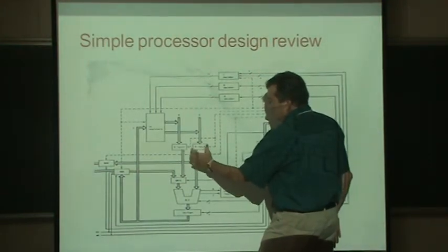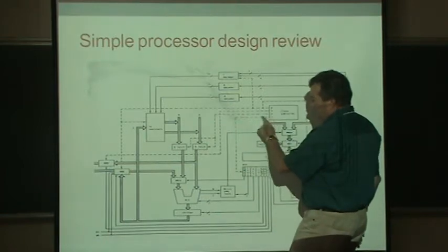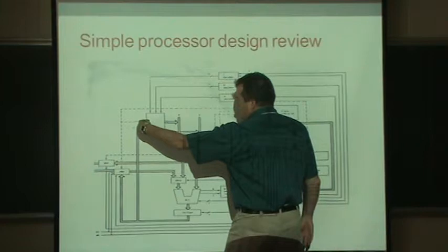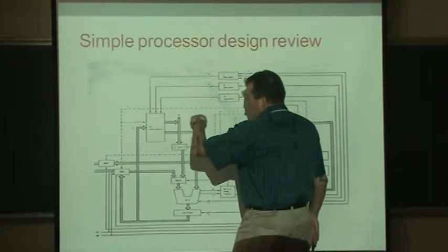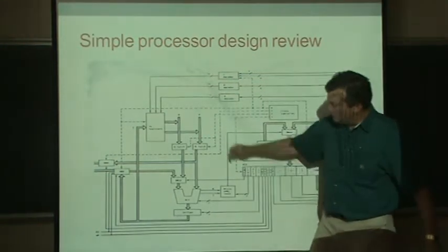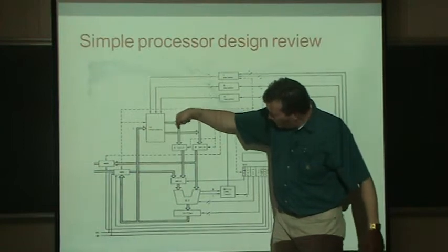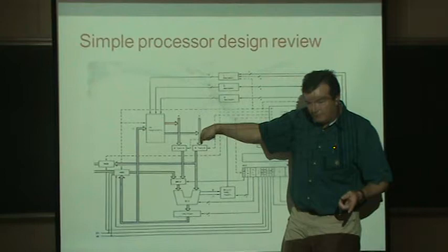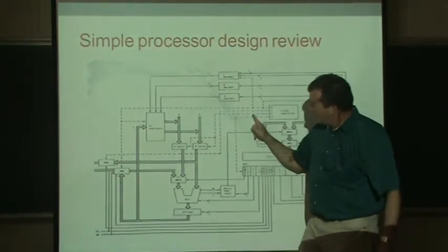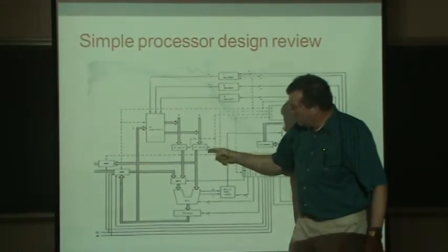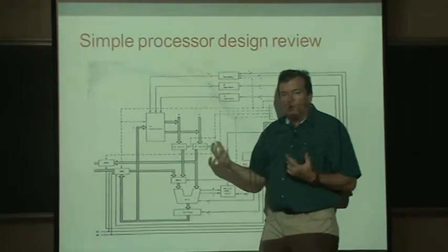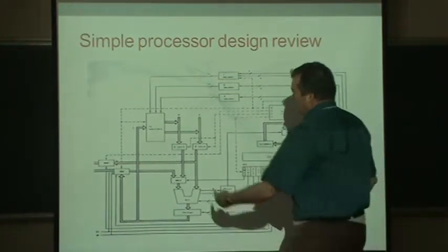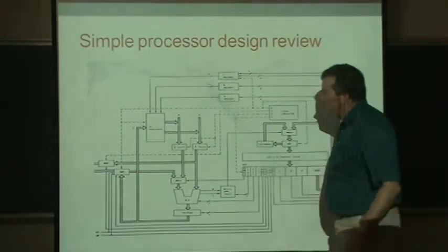So for example, task number 2 or stage number 2 of our instruction is to open up these 2 latches and let the value from the first step, let the registers that are inputting into these 2 latches be selected. So the bits are coming through in the first step. The bits that are coming into the registers are done in the first step. And then in the second step, we turn this wire on, which allows these latches to open up and accept a new value. That has to be done after the values are coming out of here.